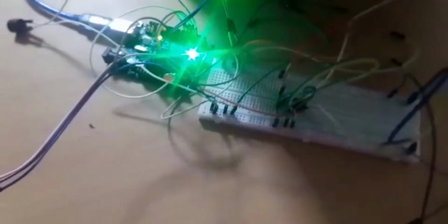So there is a green LED here, there is a red LED here. If the temperature on this temperature sensor, which will go under the laptop, goes above a certain limit, which is explained in our explanation video, the red LED will light up and this buzzer will ring. So I'll just explain the circuit in a very limited manner.